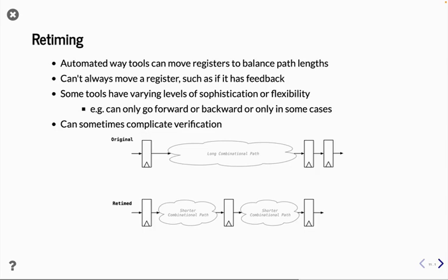And so there's actually a regression in performance from ICE to Vivado, and Vivado's been around now for 8 years, and it still seems to not be fixed. And so it depends on the CAD tool. For the open source CAD flows, I haven't tried them as much for this particular optimization. I believe some of them can do it. Who knows how effective it is.